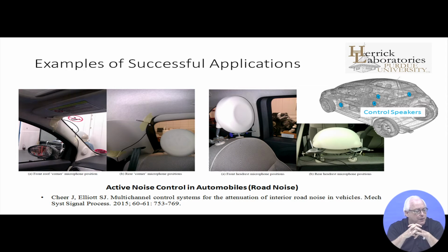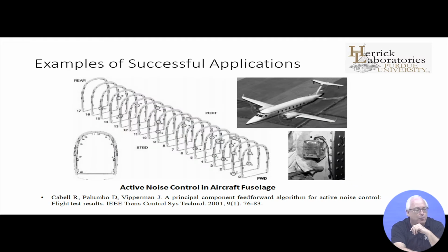So lots of noise sources, and in principle, you have to be able to generate canceling signals that are coherent with the various signals. So if you've got 10 incoherent sources, it becomes a bit of a challenge to measure reference signals related to all of those and to get them processed in such a way that they interact properly in the interior to reduce the sound field. So this is still a big challenge to make this kind of thing work properly.